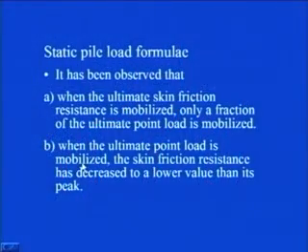The resistance developed at the tip of the pile will go on transferring to the point bearing resistance, and in that process, at any particular point of time, the skin friction resistance value will always be less than its peak value. So that is the second point we need to keep in mind: when the ultimate point load is mobilized, the skin friction resistance will be reduced to a lower value from its peak value.